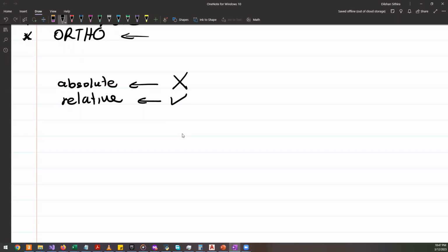These are Cartesian coordinates where you input the x coordinate and y coordinate. I hope you remember, we used the at symbol in front of the coordinate, say @10,5. You don't use parentheses to indicate the coordinate is a relative input.